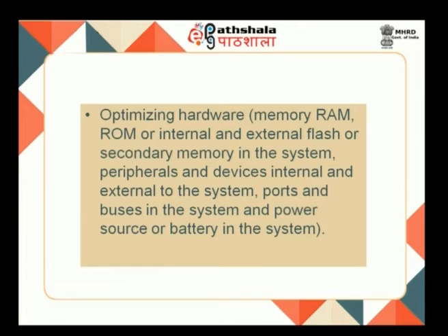If I am reducing the hardware, the cost is also very less, and the power requirement is also less. If I am making a standard product, I know very well the application for which I will be making it. So, if it is a dedicated application, I need only this many ports or only this device, and I will provide only those things, no more than required. That will minimize the hardware part so that the cost is reduced. At the same time, because the hardware part is reduced, the power requirement is also simultaneously reduced.